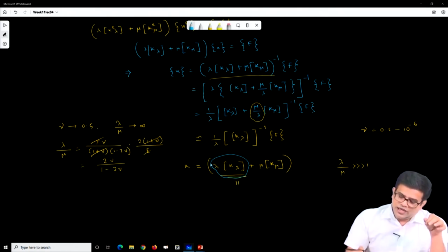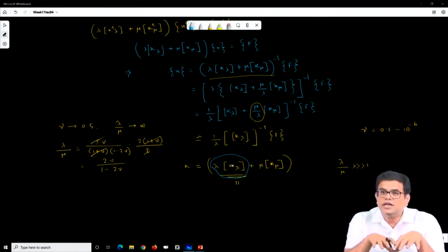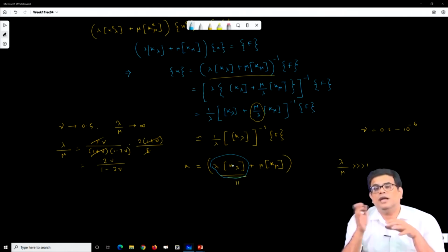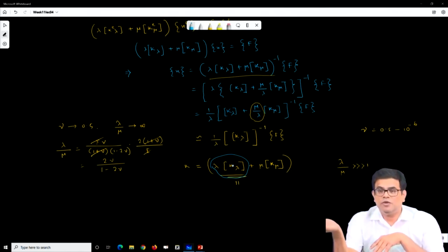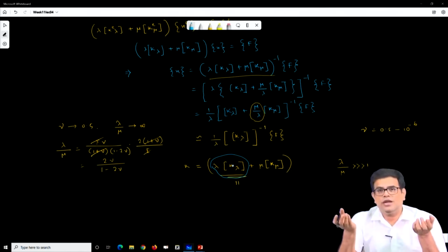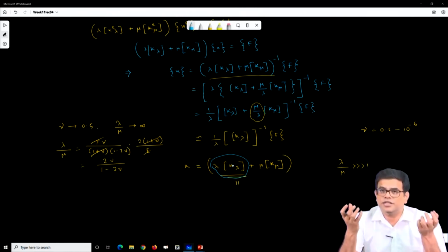So, what we generally do is integrate this with a reduced order quadrature, and the mu part, that is the deviatoric part of the stiffness matrix, which is responsible for the deviatoric deformation, we integrate fully, so that we do not introduce stiffness singularity in the stiffness matrix.